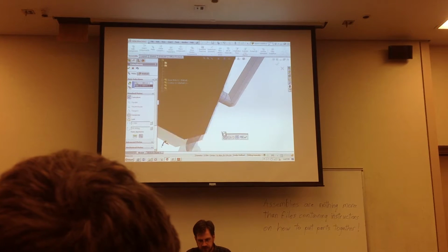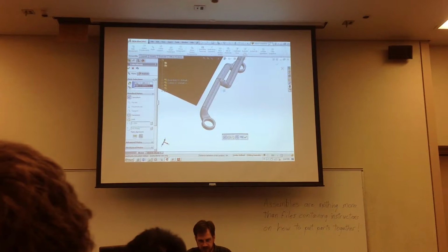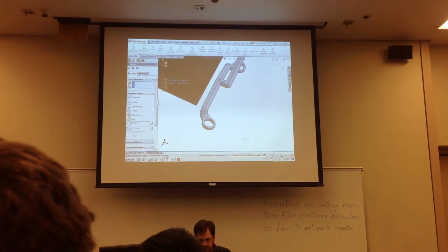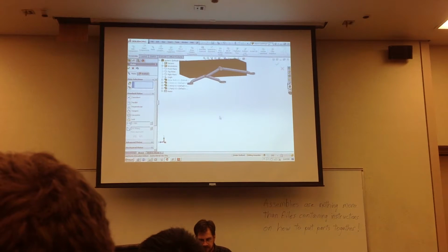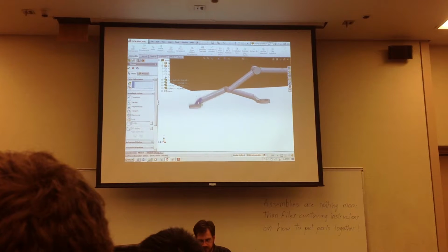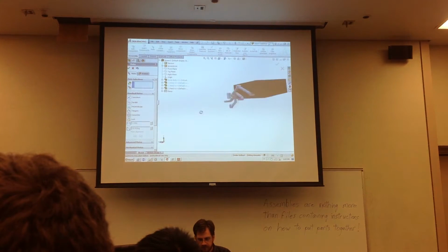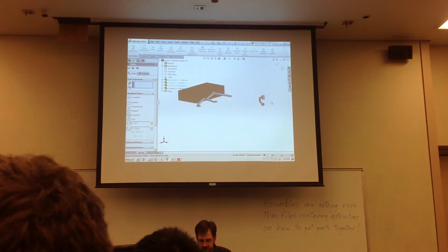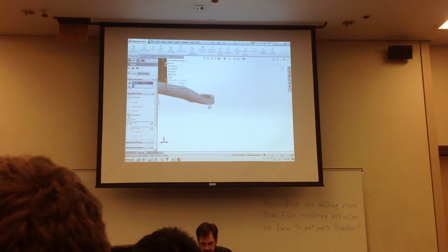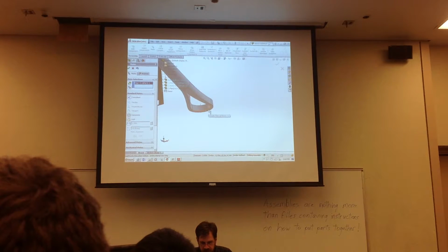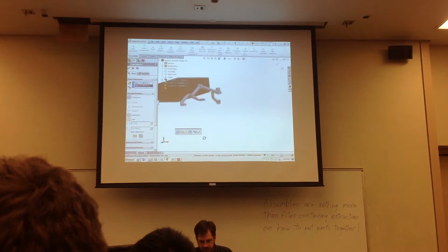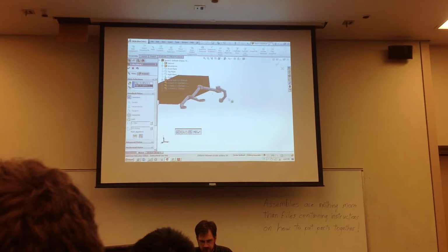Take that edge, okay, that brings it down into position. Those are aligned correctly. Now this arm is also free to rotate, but it's going to stay attached to Arm 1. Now let's do the same thing with this arm. I'll take that lower circular edge and mate it to that lower circular edge of that receptacle. Okay, and it's free to pivot.